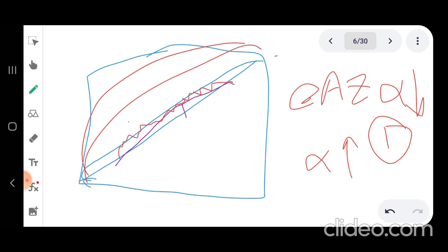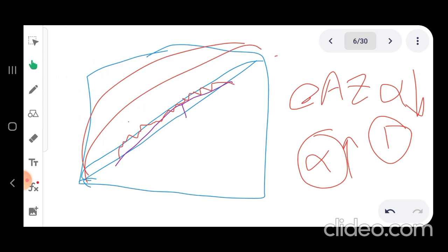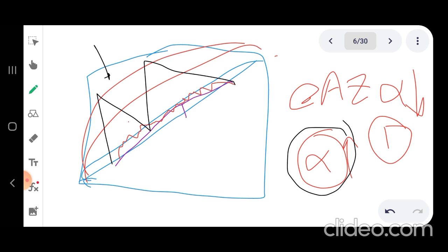Rather, suppose you have a high relative volatility, in other words, a high difference in the boiling point. So you will get a lower number of trays. Focus on this curve, for example. Let's start here. We get 1, 2, and that's it. Only 2 stages. So you can see that the higher the relative volatility, in other words, the higher the difference in boiling point, the easier the separation by distillation is, and vice versa.